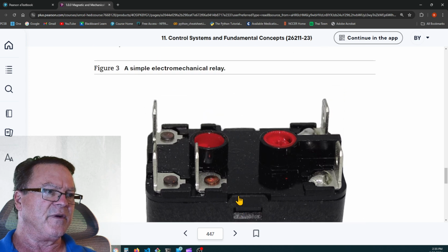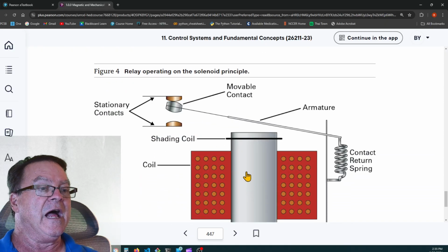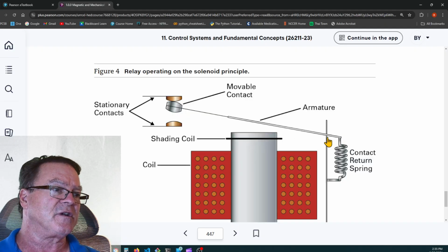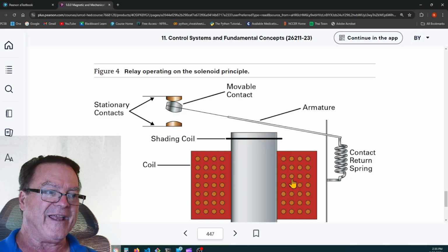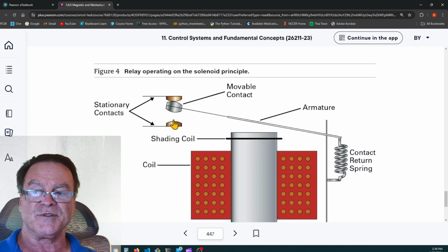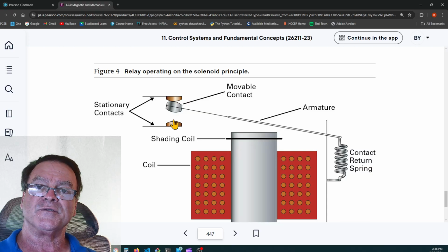Electronic relay. But all right. This is a smaller relay, and they actually have two position switches. This contact is going to make position with two different contacts. So when it's de-energized, this upper contact is normally closed, and this lower contact is normally open. When we energize this relay, those two contacts change state. The normally closed contact opens, and the normally open contact closes. So you can actually use them for two separate things, normally open, normally closed. All right.